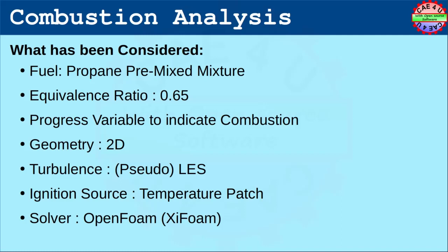Due to computational resource availability, we have to use a 2D geometry and the turbulence model used is LES. Of course, LES is applicable only for 3D geometry, so this is a kind of pseudo LES. Surprisingly, the LES model used in this analysis seems to capture the qualitative picture of the combustion process very well.